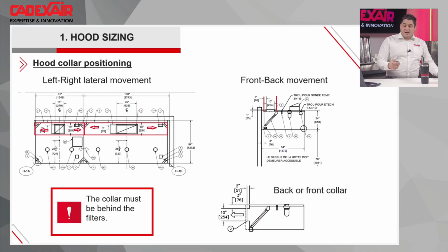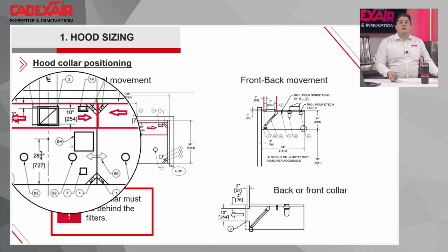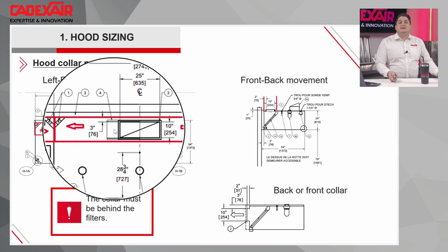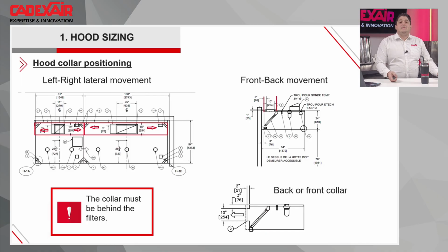We will use the sliding damper in that case because the hood on the right has more airflow than the hood on the left. So we will slide it inside of the dog collar to simply blank a part of the dog collar. And this is a listed product, just to be sure. So it will create restriction inside of the dog collar, so it will help the air to go inside the other hood. So that's a way to make it happen.